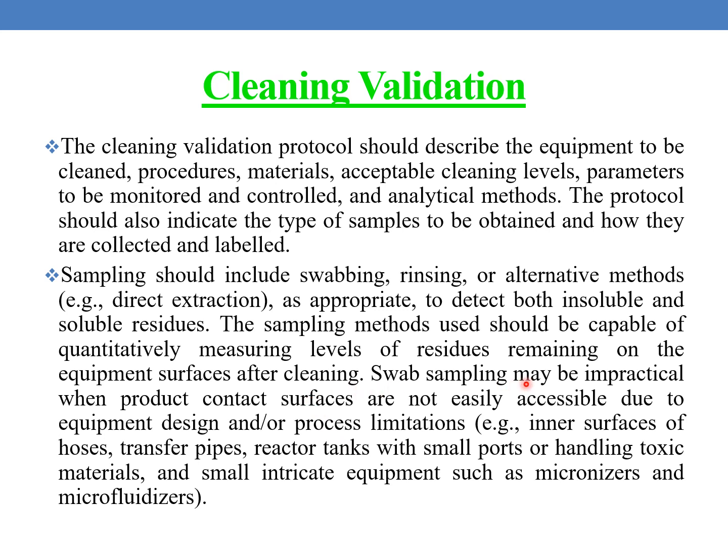The sampling method should be capable of measuring levels of residues remaining on the equipment surfaces after cleaning, and swab sampling may be inappropriate under certain circumstances.